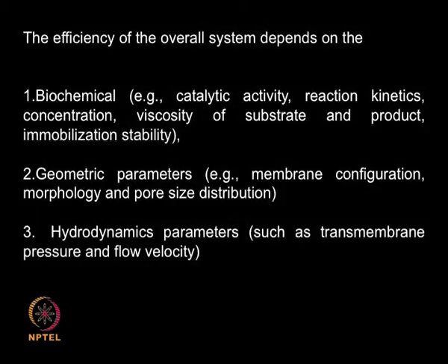So the efficiency of the overall system will depend upon the biochemical parameters, that is the catalyst activity, reaction kinetics, concentration, viscosity of the substances, product, and immobilization stability, how stable is this enzyme when it is immobilized on your membrane. That is a very important point to consider because enzyme may lose its activity when you are trying to immobilize it on the support. Then the geometric parameters, the membrane configuration, is it a flat plate, is it tubular and so on, the morphology and also the pore size distribution.